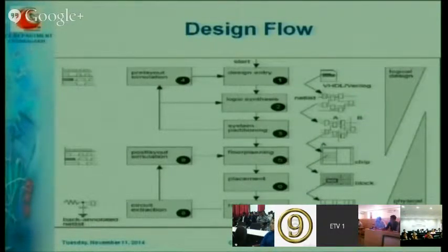Once you have entered this program code, the next thing is this code is converted into RTL, register transfer level, where your code will be converted into a number of registers along with its netlist connection. Then the next part is the partitioning of design, because the whole design cannot be active at the same time. So we can partition our design depending upon its functionality.